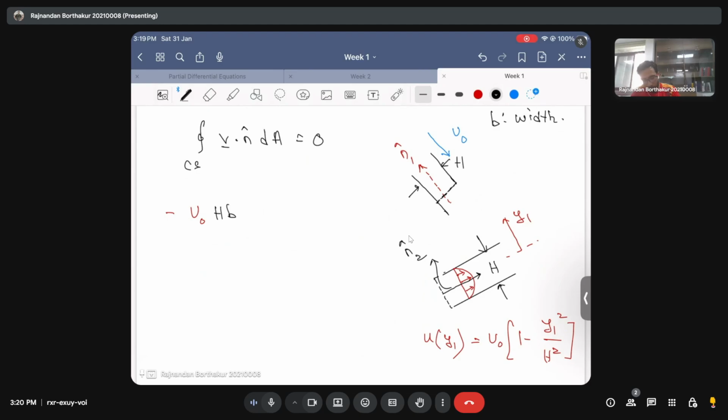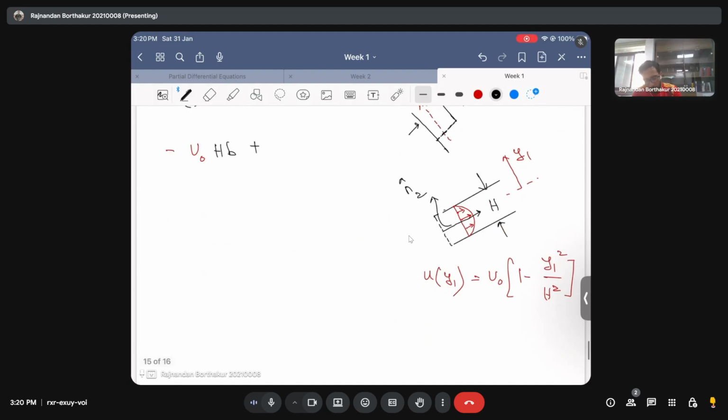Okay, so then this dot product would simply give you plus, but here is something that you need to understand. The direction is taken care of, but you need to understand that when you move along your y direction, or y1 direction to be precise, you are actually seeing a change in the velocity profile. Your velocity profile, which has a magnitude of u naught at y equal to 0, is changing from u naught to 0 when we move along this y direction,